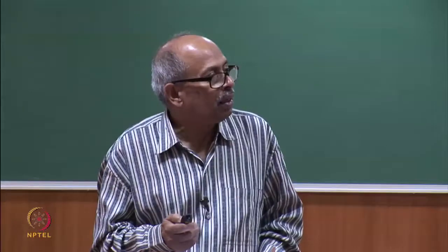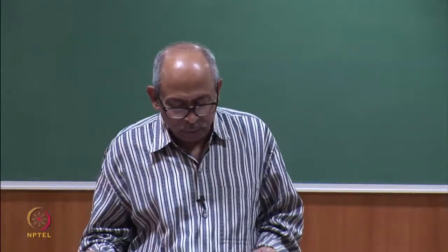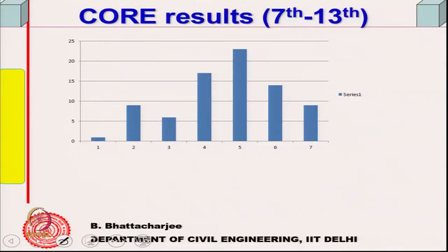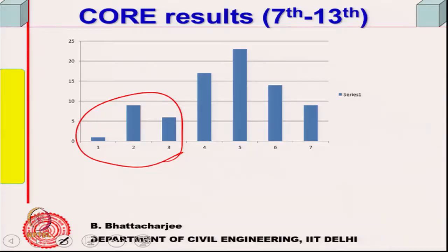of strength, and it showed again 2 peaks from 7 to 13th floor, the same building. 7 to 13th floor had bad concretes that we have seen. We started examining it more, and after a log strength plot we could find out some concrete is bad, somewhere something went wrong, the rest of the concrete is perhaps okay. 2 different distinct peaks we found out.